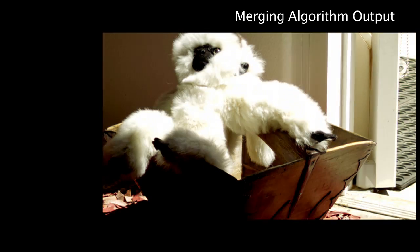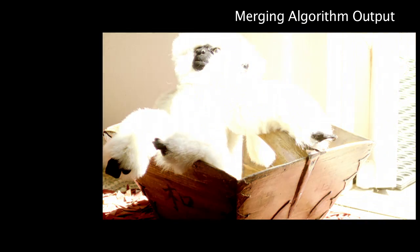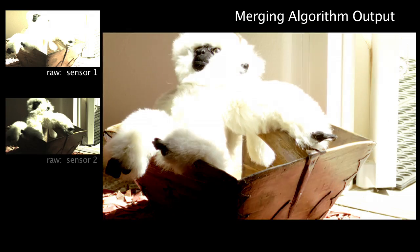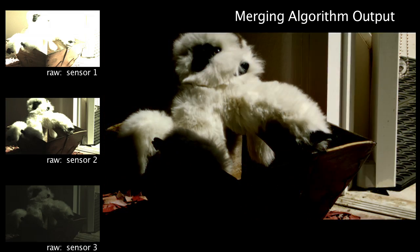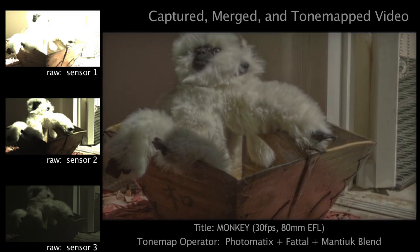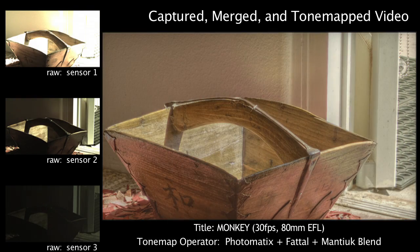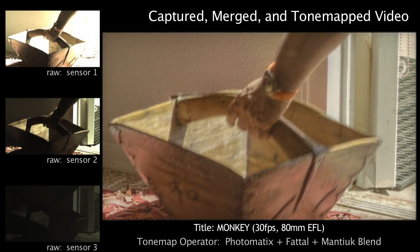The result of our fusion algorithm is a true HDR image for each frame of video, which can be converted from pixel values to scene irradiance values using the camera response curve. Each HDR frame produced by our system contains the entire exposure range captured by the camera, covering over 17 stops.